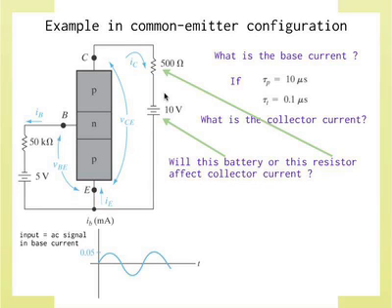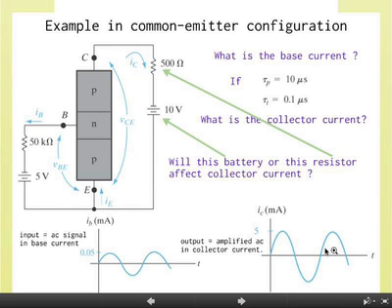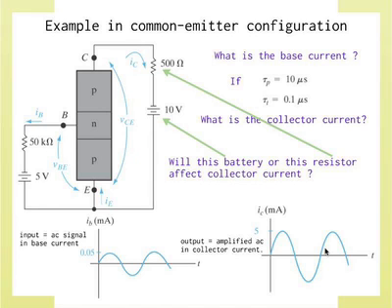So as a result of this, what we can do is amplification, which is the whole qualitative picture that we're talking about so far. If you put an AC signal to the base current, you can do that by putting a small AC signal to the base bias voltage. So in a transistor, if you have an analog circuit, communication circuits, whatever, you send in a signal, audio signal, whatever. That goes in there. What comes out on the collector side would be the amplified version of it. And you can do your signal processing, whatever. So it's an ideal amplifier, essentially.